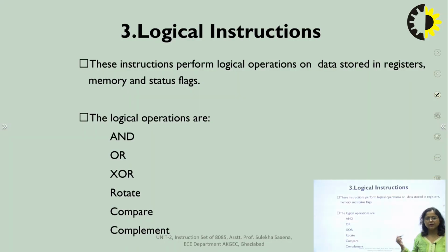So these are all the arithmetic operations, where only 4 arithmetic operations are there in 8085. For arithmetic operations, plus, minus, increment and decrement are specified. Now we move towards logical instructions. In case of 8085, the following are the logical instructions: AND, OR, XOR.